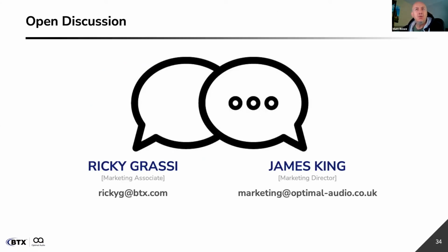That question suggests audio there, doesn't it, between controller and amps? That's standard balanced line, Cliff. So between controllers and amps, normal balanced line regulation applies. So pretty much as long as you like, but the longer the cable, you'll start getting some HF attenuation if you get to really long lengths.